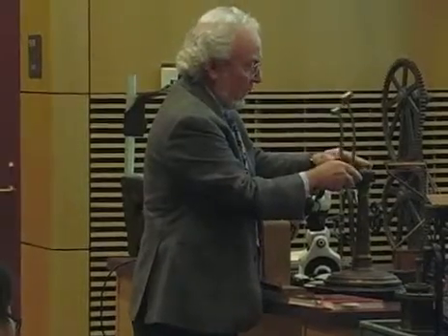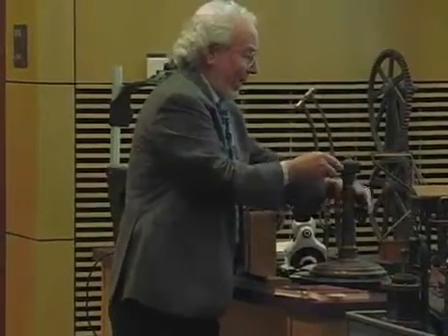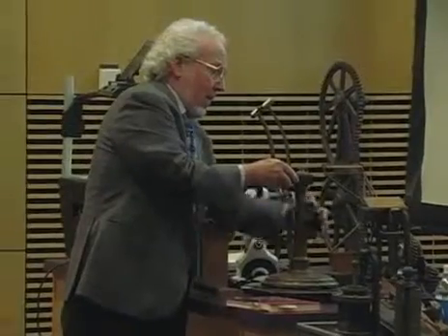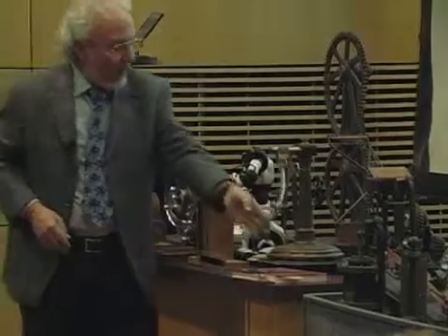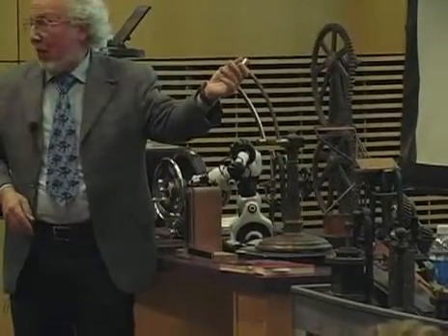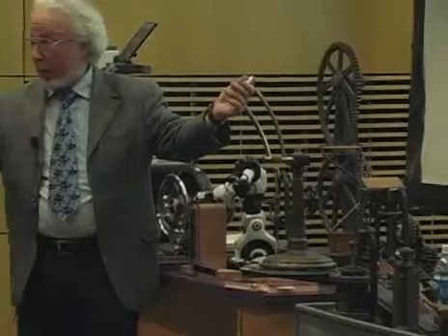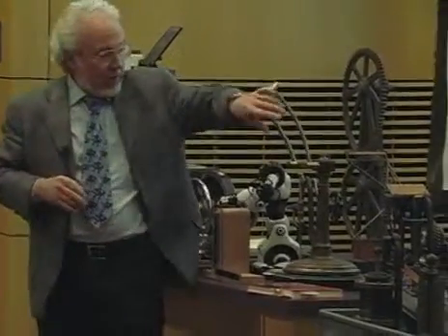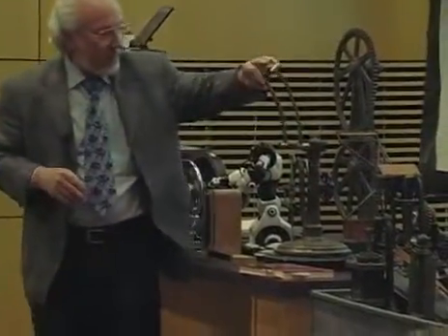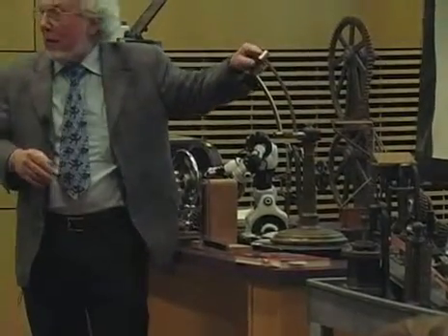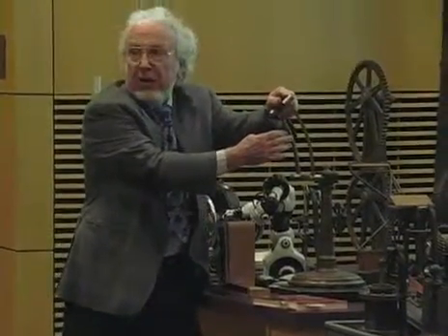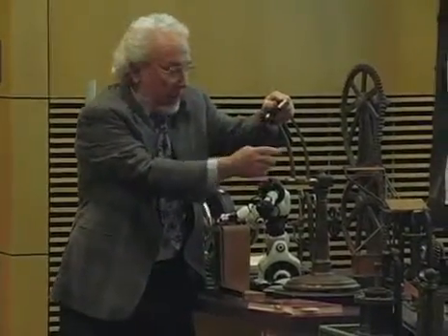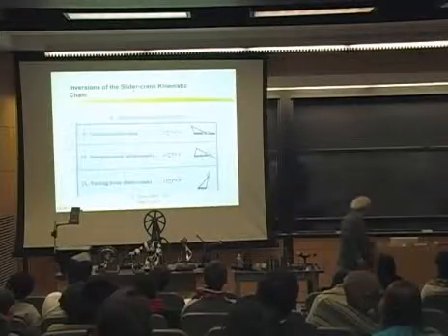So if we ground one of the other links, you see, now we have both of the links can go around. In the first one, when we grounded it, we turned the crank and we got a rocking motion. Here we get both of them. This is called a drag link mechanism. And so from the same kinematic chain, chain being the sequence of links and joints, we get different mechanisms. And we can see this in the slider crank, I think, in the next slide here.